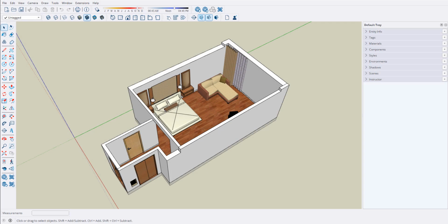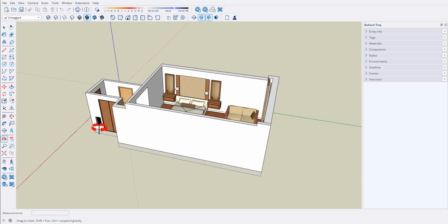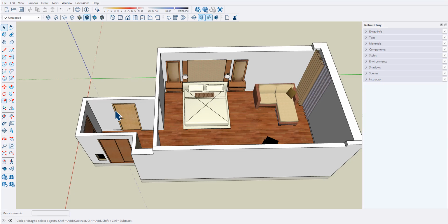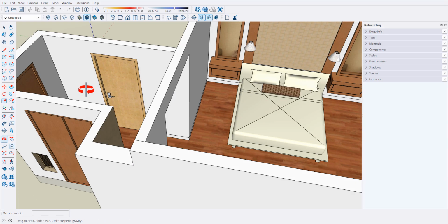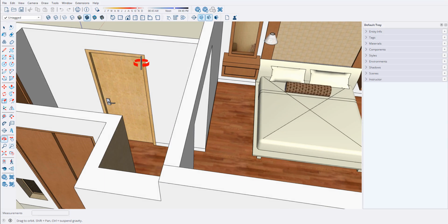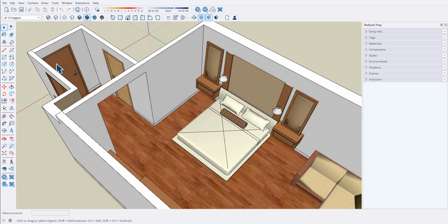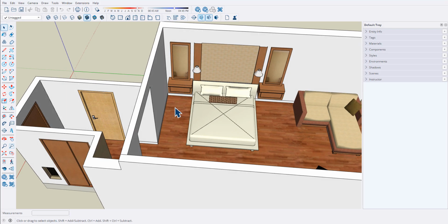Let's continue working on the hotel to kind of bring it up to speed and have all the materials be complete here. And one thing we notice when we bring in things from the 3D Warehouse, they may or may not match our design intent. This door, for example, isn't quite the right material. It came in with a material, but it's not the right material for a scheme. You can tell that it doesn't match. What we can do is replace this material, just like we did the countertops.